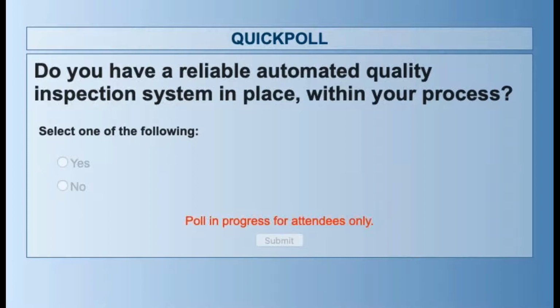We've seen two different thought processes on inline quality inspection. Some of the folks that we've seen have pyrometers, or vision systems, or operator manual inspection. But typically it's not in line right after the dispenser system. It could be down the line of the process, or the robot has to flip around the product, as in the bathtub case, where they're doing a visual inspection. But it's very difficult. They can't see heat, so what they're looking for is gloss or reflection from the adhesive. I've seen a lot of different things like that.